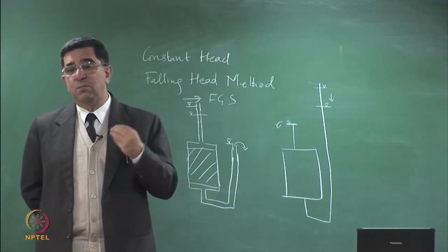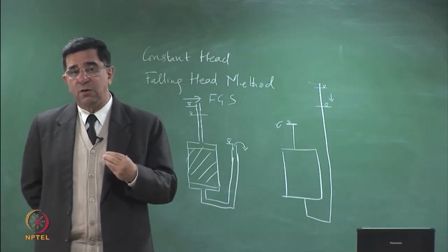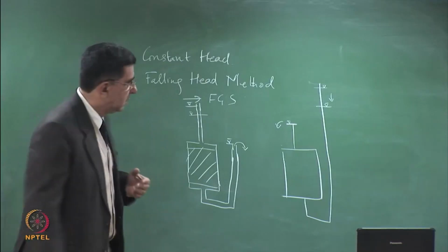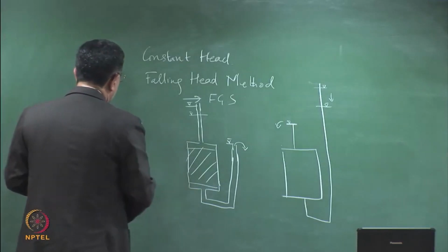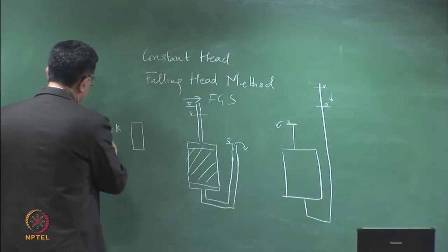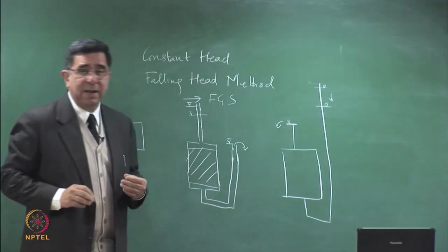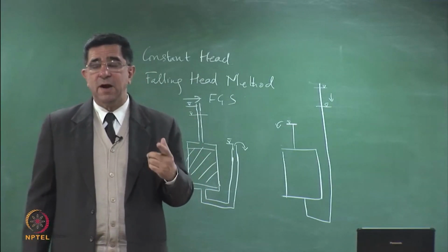Yeah, so the word is we do back pressuring of a sample. We force the air to get dissolved in water by putting extra pressure in the sample. So in a triaxial test, you are using back pressure to saturate the sample, and you use a parameter called the B factor. And how much should be a B factor ideally?